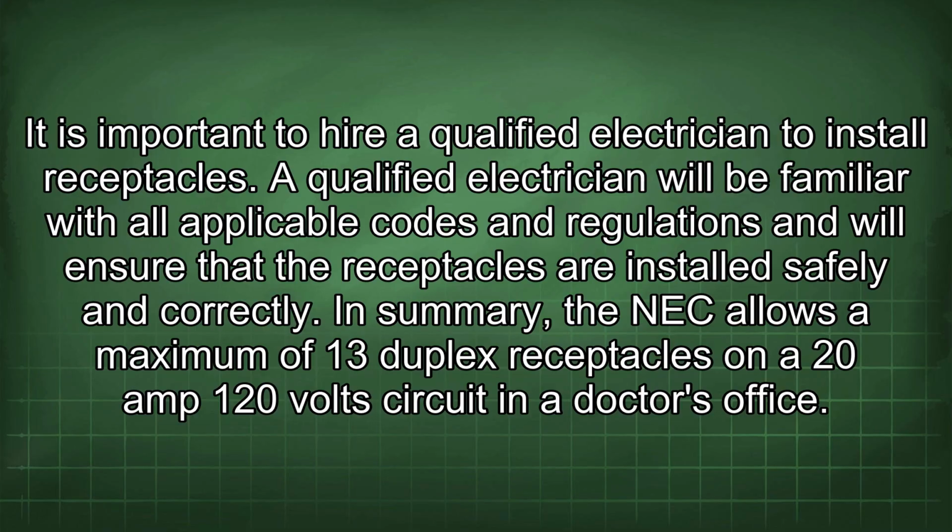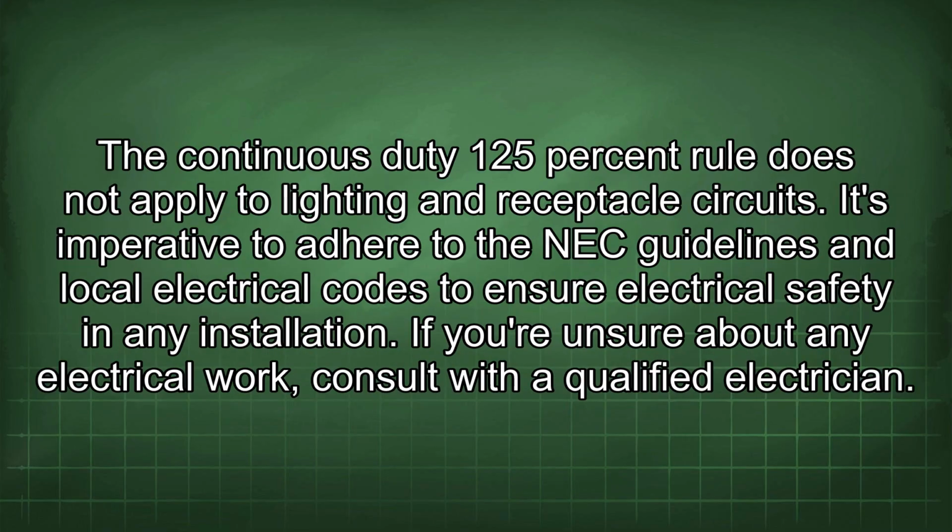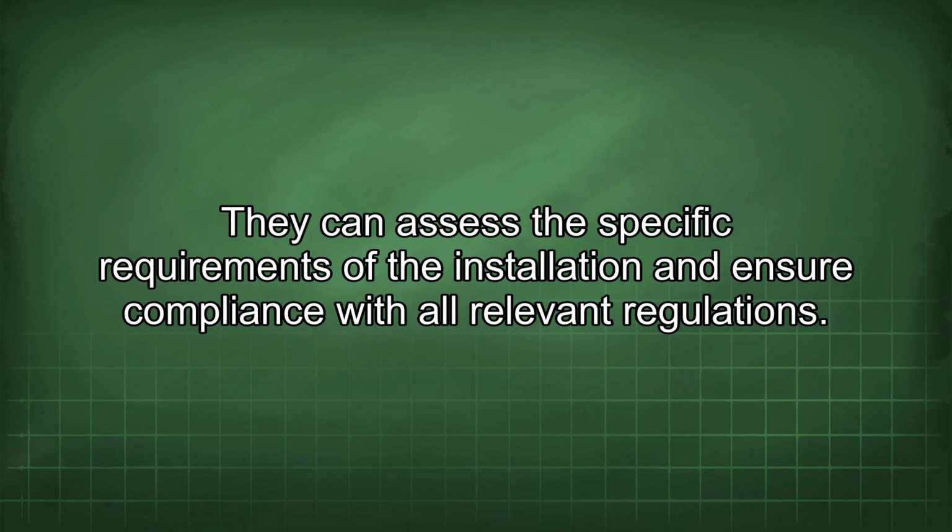safely and correctly. In summary, the NEC allows a maximum of 13 duplex receptacles on a 20 amp 120 volt circuit in a doctor's office. The continuous duty 125% rule does not apply to lighting and receptacle circuits. It's imperative to adhere to the NEC guidelines and local electrical codes to ensure electrical safety in any installation. If you're unsure about any electrical work, consult with a qualified electrician. They can assess the specific requirements of the installation and ensure compliance with all relevant regulations.